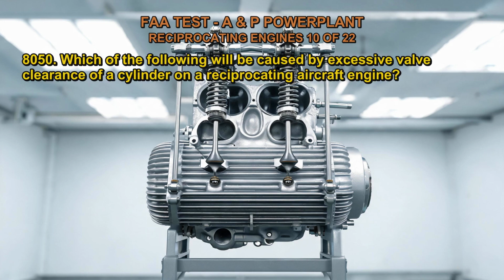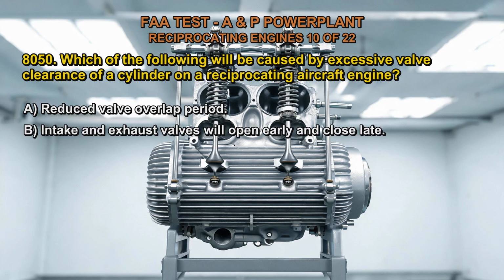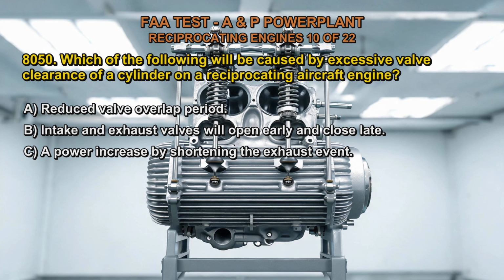8050. Which of the following will be caused by excessive valve clearance of a cylinder on a reciprocating aircraft engine? A. Reduced valve overlap period. B. Intake and exhaust valves will open early and close late. C. A power increase by shortening the exhaust event. The correct answer is A.